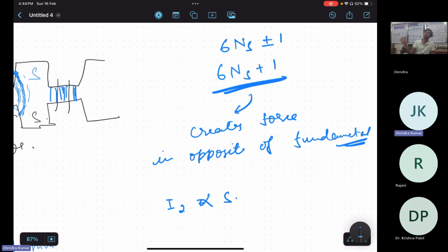It tries to move smoothly forward, but it does not happen very smoothly. So that is why it is called crawling. And it happens because of the seventh harmonic and also at lower speed. And to be precise, at 1/7 of the synchronous speed, right? You can either Google it or see the textbook to understand it in detail. But that's, in a nutshell, whatever I have explained.